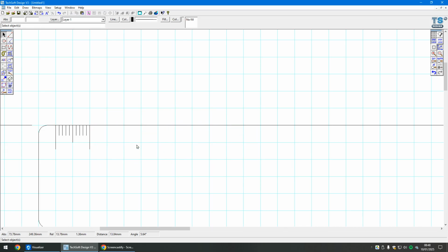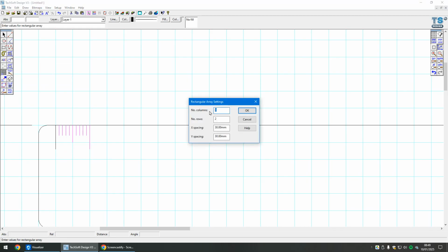I'm going to delete all those centimeter millimeter markings. I'm going to select again just the 1 to 10 millimeters, and I'm going to come to the transformation tool, which is tool A7, right here, transform. I'm going to hold the mouse button down, and I'm going to go to draw a rectangular array of the selected objects. And I'm going to have it so that this is going to have a total of, now I want to have here 18.